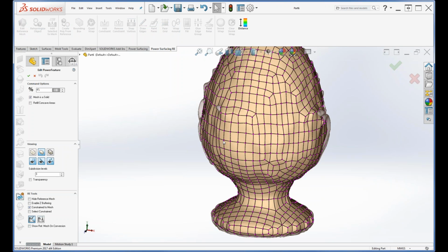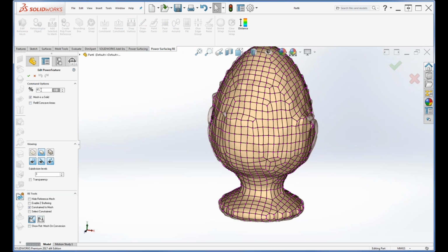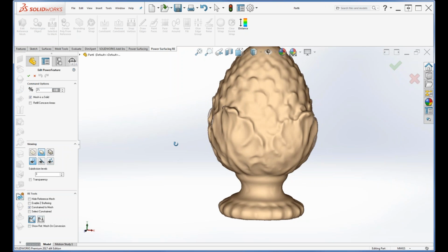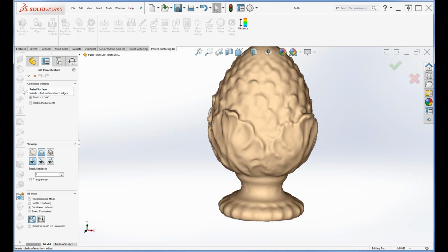Okay, I couldn't even do that by hand that quick. So you look at it though and you go, well, that's not real accurate, because right now it's on 4% for the size. So I'm going to drop it down to maybe 2%. And we should start seeing less stuff coming through. You can see that. So it starts to get slower here, so I'm going to turn off both the vertices and the edges on it, which also lets you see more detail. And maybe I'll go down to 1% on this one. Now the problem with getting too tight onto your reference mesh is if it was a messy reference mesh, you're going to get the messy stuff along with it. So as soon as this thing's finished doing its 1%, I'll show you some of the changes we've made that make cleaning up a reference mesh really nice.